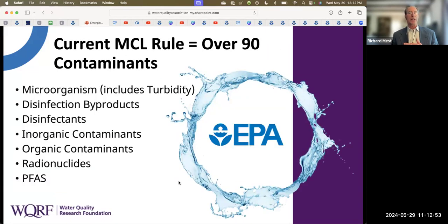Currently, we have over 90 contaminants that are regulated through the Safe Drinking Water Act. Microorganisms, which also includes turbidity, disinfection byproducts, disinfectants, inorganic contaminants, organic contaminants, radionuclides, and now we have the most recent PFAS class of chemicals.